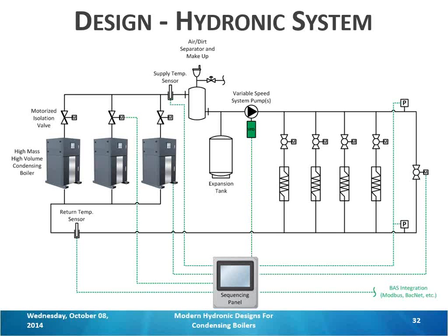If there's any consulting engineers here, do you have any experience on what you're sizing systems around in terms of delta T? 30? Yeah, I find it's pretty typical to see 30 or 40.